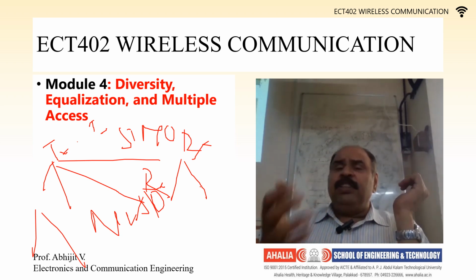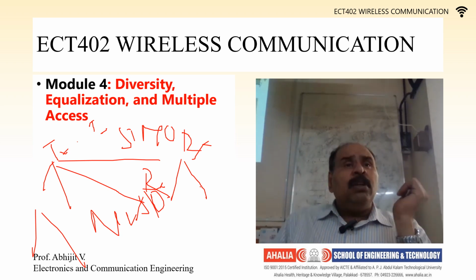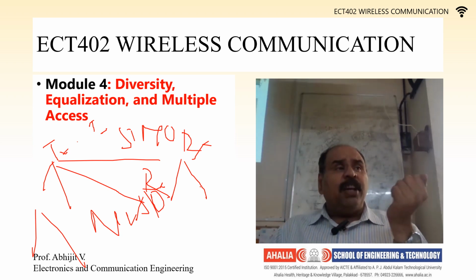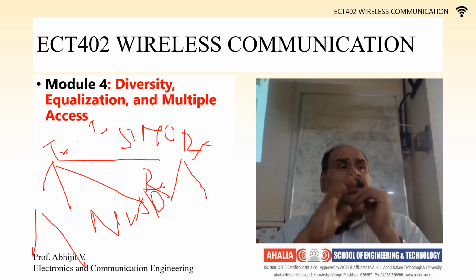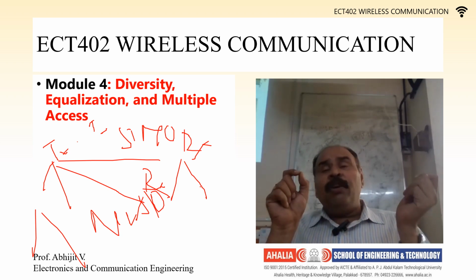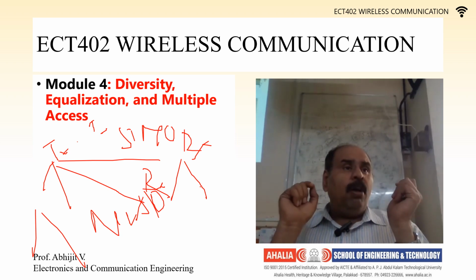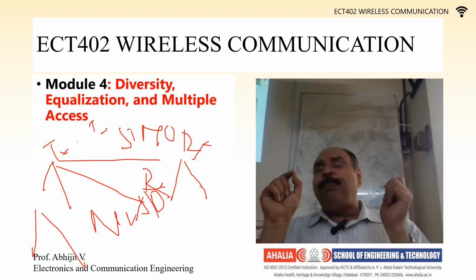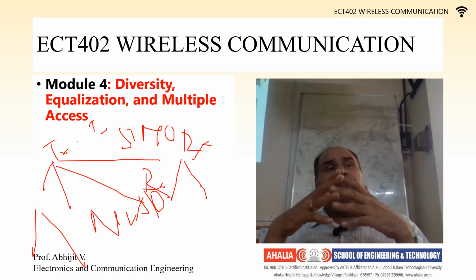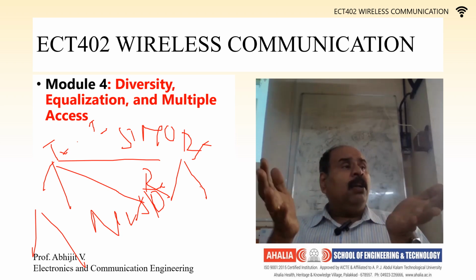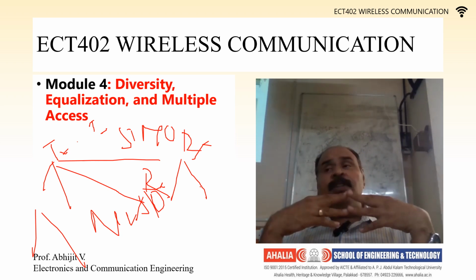Now my question is, why do we want to have multiple inputs? Why is the concept of diversity being developed? The basic necessity for diversity is to counter fading effects. Fading reduces the power of the transmitted signal. So in order to compensate for fading, we are using different diversity techniques.